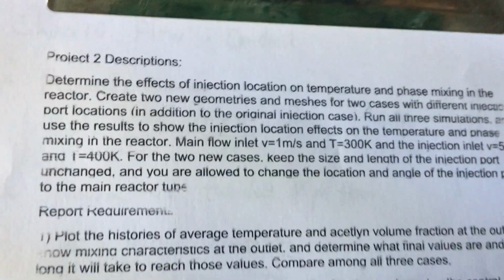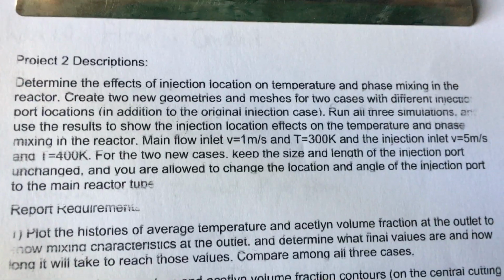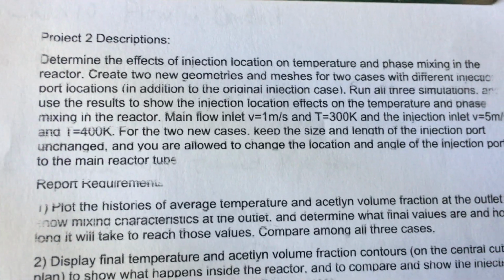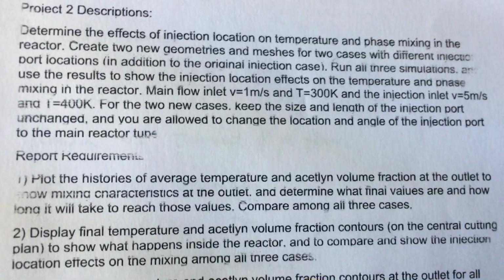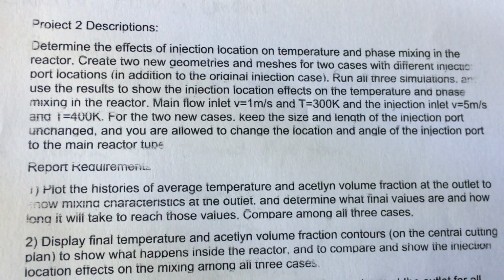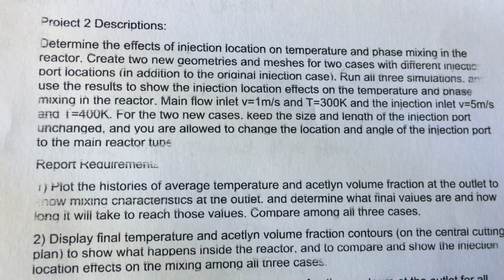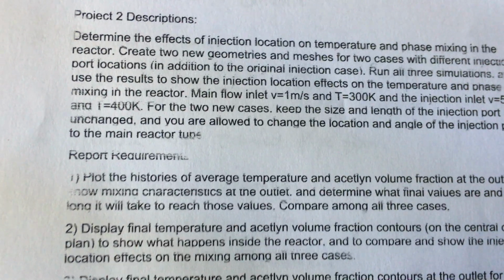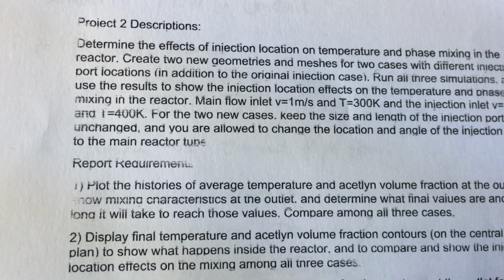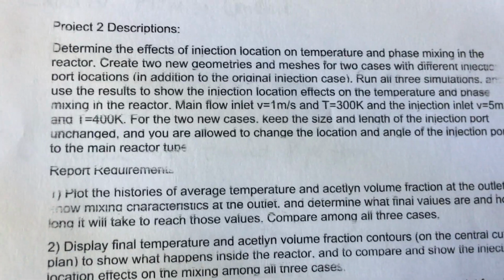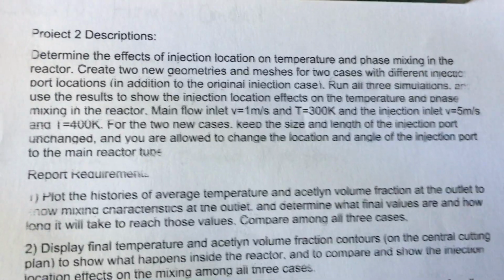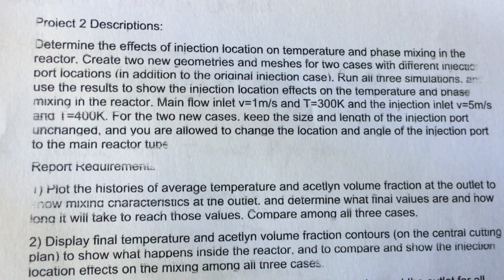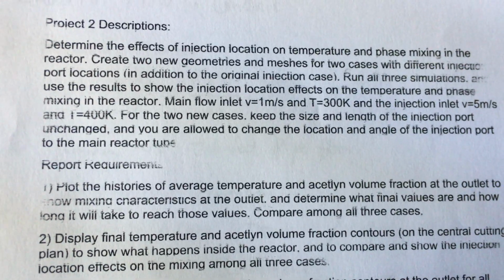The other thing I want to talk about is that this fluid simulation problem is not just single phase flow, not just one fluid. You have two fluids, so in the tutorial I show you how to specify the multi-phase flow model. You have two different phases, and the two phases occupy the entire volume of this reactor. We use something called volume fraction to determine the percentage of volume occupied by each phase.